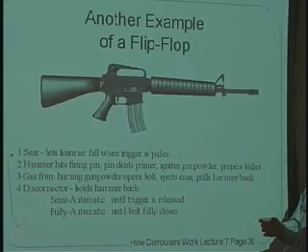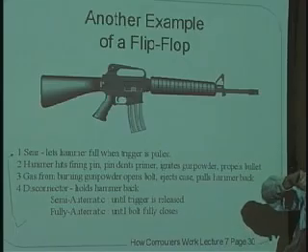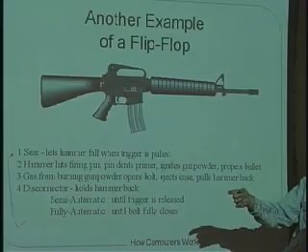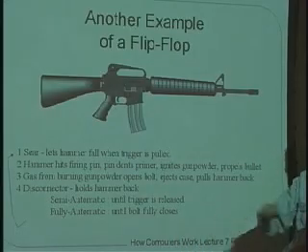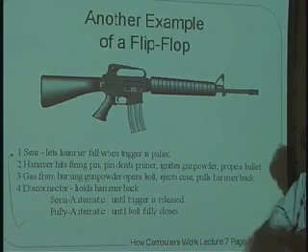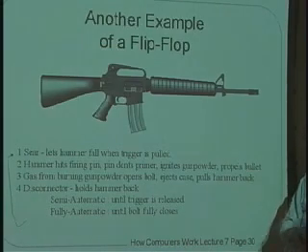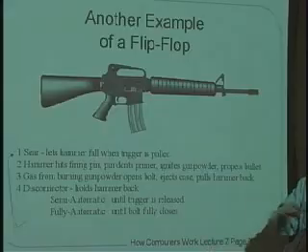You will notice that when you let go of the trigger, it goes click. And the click that you hear when you let go is actually the sound of the flip-flop going into the other state. And then when you fire it, of course, it goes bang, which is, you know, the other state transition. But you do hear the state transition backwards too. And that's why only one round comes out at a time, because of a flip-flop.